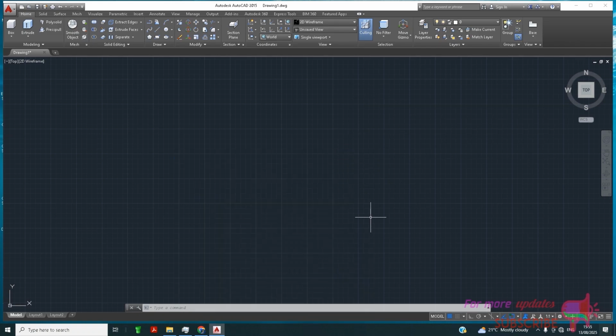What's up, dear viewers? In this video, I will show you how to draw a tent structure in AutoCAD. This is another AutoCAD 3D tutorial. So I'll go to that setting, make sure you're in 3D modeling. Then you go to Home, make sure your view is Southwest or Isometric.